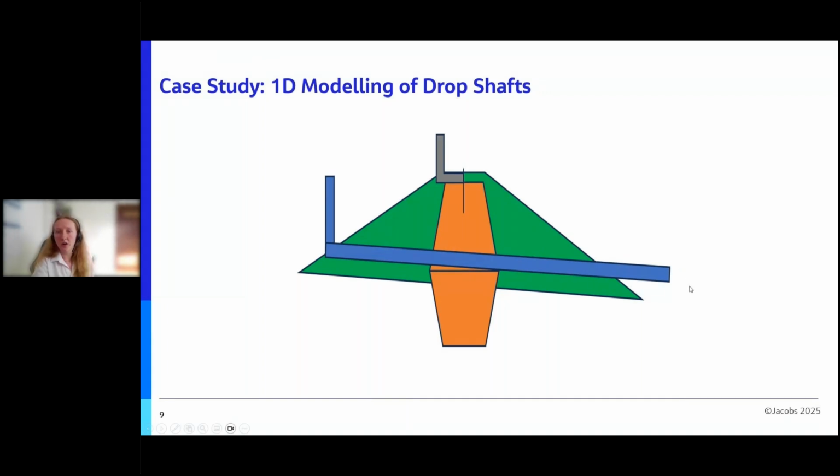Initially, the system works like a weir around the circumference of the entrance, but as water gets higher and flow rates increase, water level hits the top of the culvert and there is friction loss over the full length of the culvert. From this point, water level will back up from the culvert and rise higher and higher up the drop shaft until it drowns the weir. From this point, it acts as a pipe full system and head increases massively with any small flow increase.